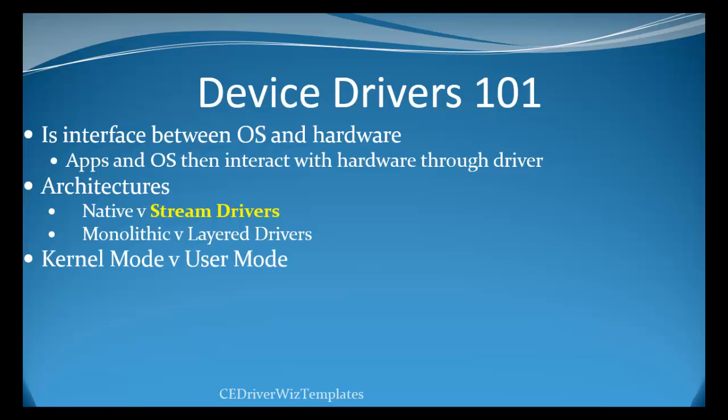The other thing with Windows Embedded Compact 7 is to consider whether the device driver is going to run in kernel mode or user mode. This option is facilitated by the wizard, quite simply. So we're looking at stream drivers. Stream drivers provide a standardized interface, standard implementation. So they all have the same basic architecture from a software perspective, which makes the implementation simpler than trying to build a native driver.